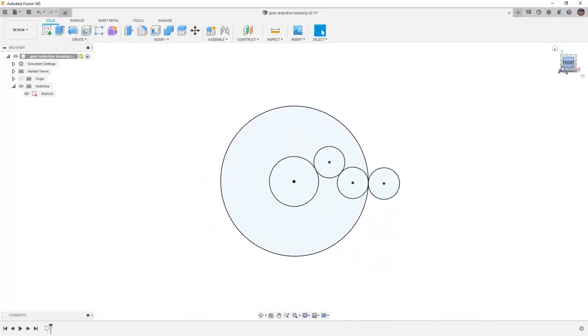I'm going to go back to a front view, and I want to talk for a second about each of these gears that we drew. These are going to be placeholder positions to get us a good idea of where all of our gears need to be. We have our drive and driven gears at the center. Our final assembly will have a common shaft that allows us to drive one of the gears and then have a bearing so that the other gear is free to rotate.